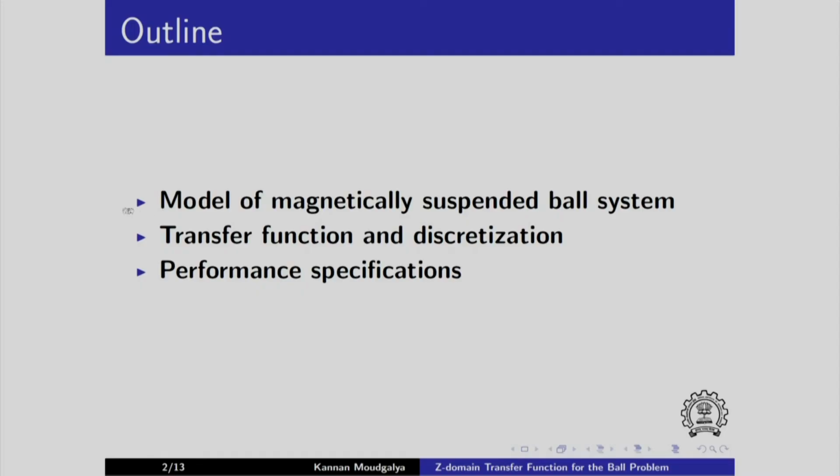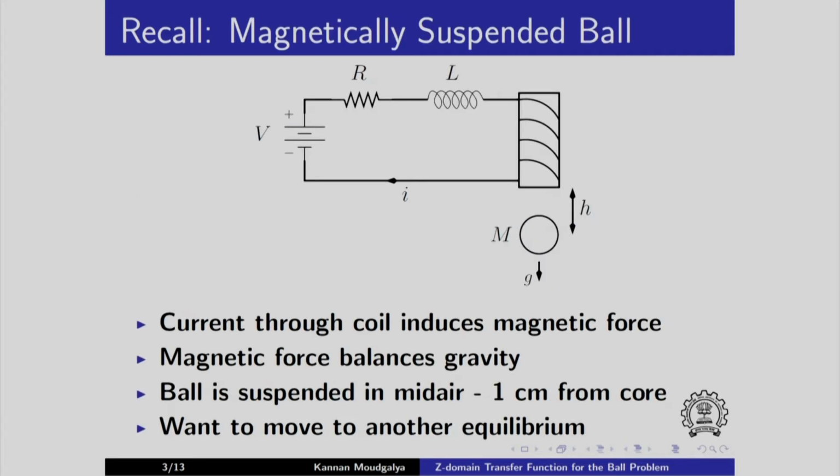Welcome to this presentation wherein we will derive the Z transform transfer function. We will start with the model of the magnetically suspended ball system. We will obtain the transfer function and discretize it. We will also obtain performance specifications.